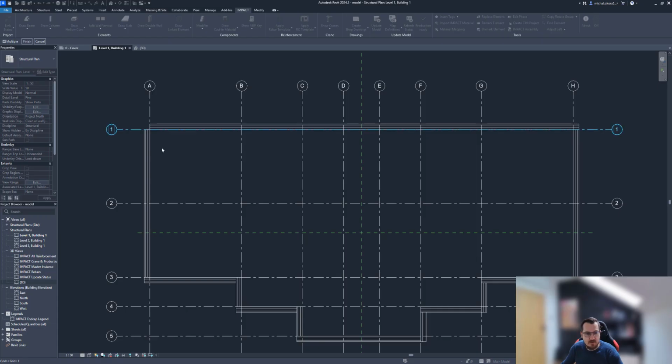I just click finish here, and with that I will need to select reference planes. So those are my Revit axes here, and I'll just select all those that I want to be used for division. I want those walls divided and those walls and this big wall divided, and just click finish.